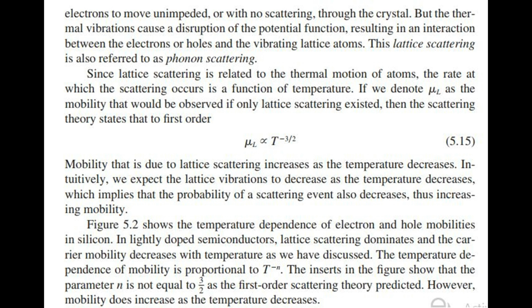The temperature dependence of mobility is proportional to T to the power of minus n. The inserts in the figure show that the parameter n is not equal to 3/2 as the first-order scattering theory predicted. However, mobility does increase as the temperature decreases.